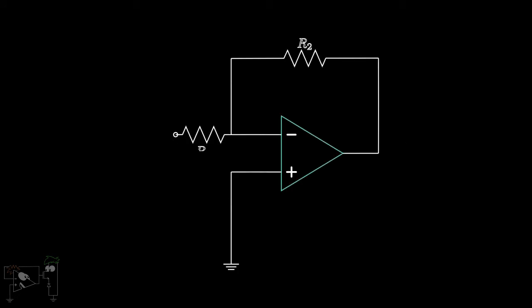In this video, we'll see how the supply voltages affect the output currents of the op-amp. Consider an inverting amplifier. Suppose we have an input Vn. We will get an output equal to minus R2 by R1 into Vn. Assuming the op-amp is ideal, there is no current through the inputs of the op-amp. However, the current at the output through R2 and R1 is minus Vn by R1.